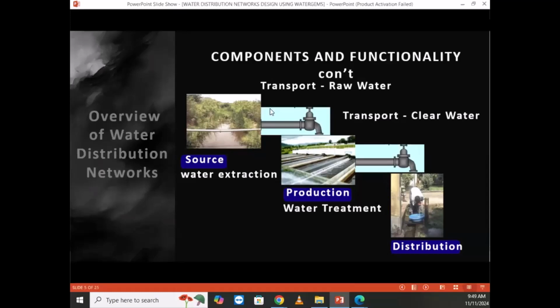If someone puts a hotel here, a hotel consumes much more water than a house, and they sized a small pipe to reach me, those people will start having problems getting water. So while designing, don't consider only domestic use as an end use. You also add some industries, you also add hotels, you also add everything which can need water.